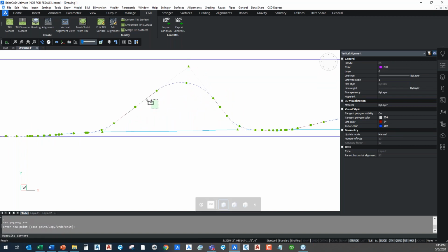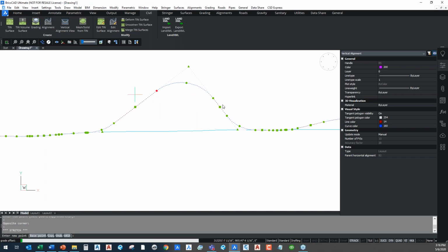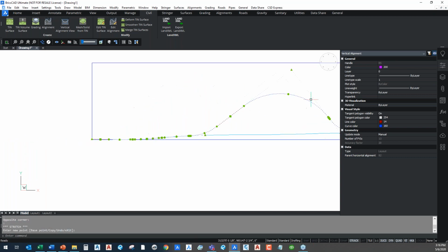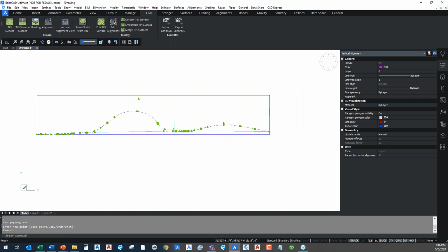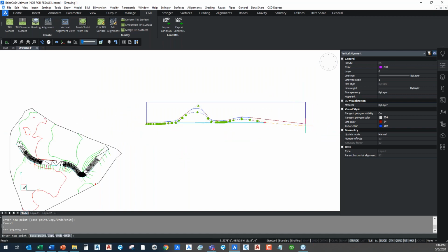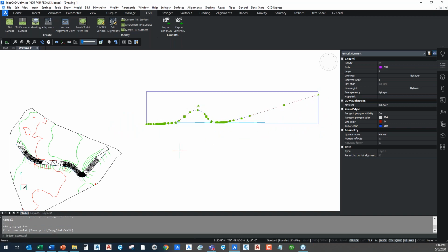I can pull the curve locations. I can adjust the vertical curves, make them higher, taller, flatter, right? Bring PVI points up, make whatever changes I need to all of these different locations throughout my alignment. And this update, this change, even to the point of going in and changing and extending this roadway. So I make it go this way, up and out, okay?